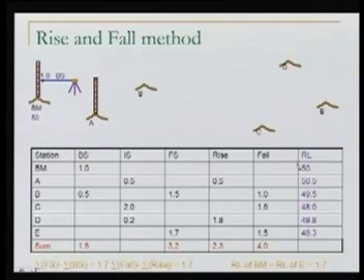Next, I take my staff to A, and I take an intermediate sight on that. Now, if the backsight is 1.0 and the intermediate sight is 0.5, then what is the relative RL of these two points, the benchmark and A? What is the relative difference between them? The important thing here is that we are trying to compare the relative heights of the points.